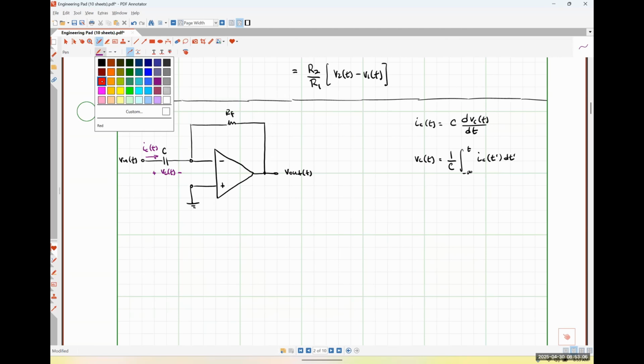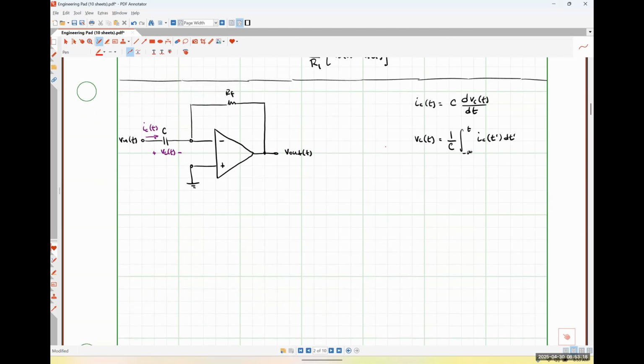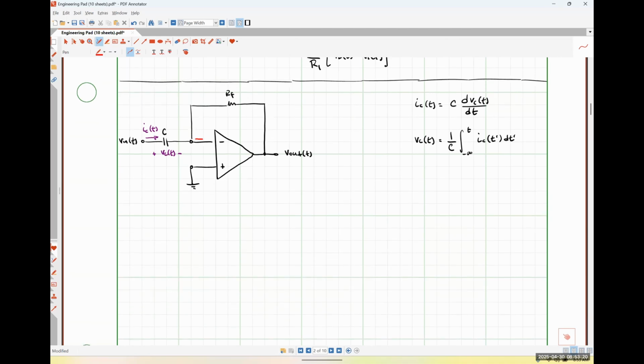And we are largely going to be able to just do that 5-step process and figure out how this guy behaves, even though we have calculus-based relationships to deal with, okay? So let's start by saying that we have 0 amps of current here and 0 amps of current here. Our voltage at our non-inverting input node is 0 volts.